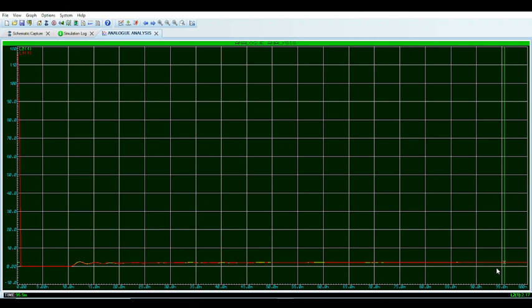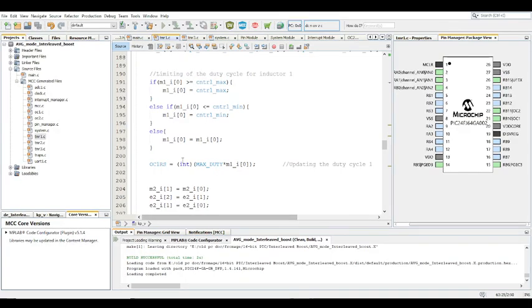You can get that and pair it up with a high resolution PWM, and you're gonna get to the voltage you want down to 1 decimal place for sure, at least to 1 decimal place. So if you want 2.2, you get 2.2. If you want 2.25, I guess you're gonna have to go higher with the ADC resolution. But let me just get back to it.